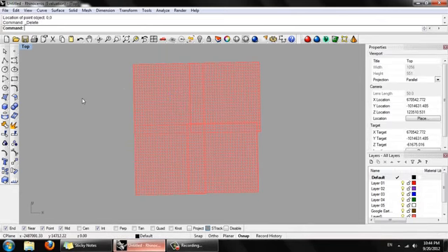So what we're going to do here is we're going to do a drape command. Just type drape, D-R-A-P-E, and auto spacing yes, spacing 5 should be fine. And we're just going to, like it says, drag a window over area to drape.